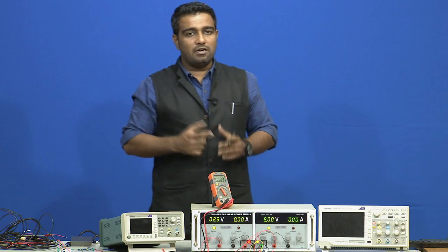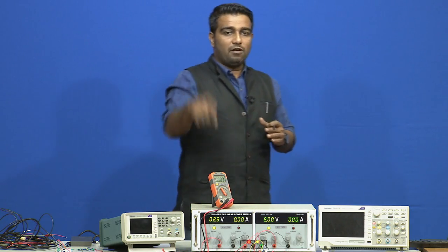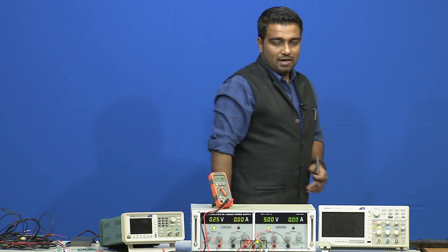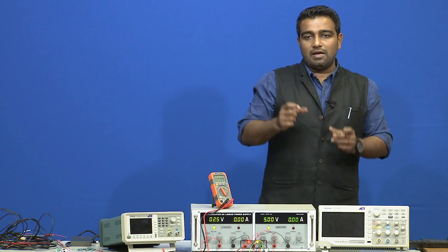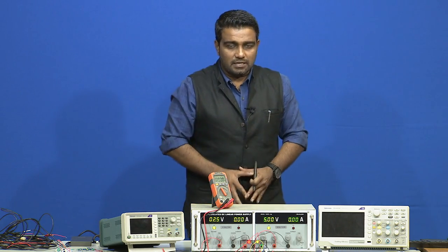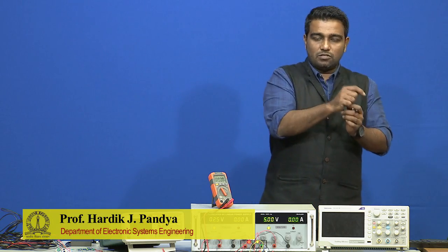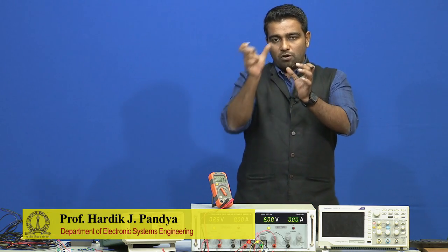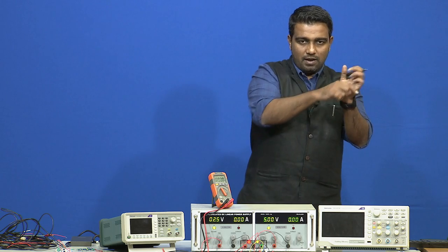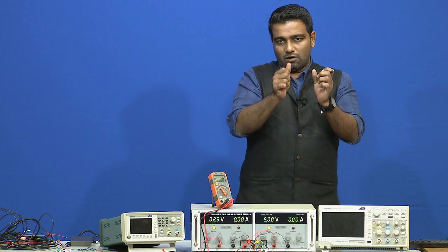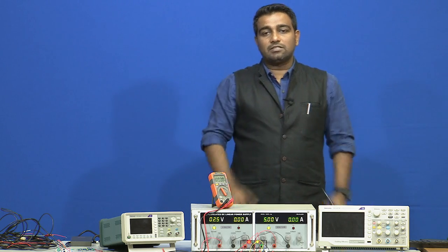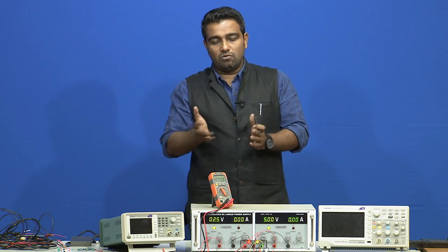So, understand this thing, until and unless you ground the circuit it will not finish, right, you cannot keep it hanging. So, same thing when we are using an LED with a current limiting resistor, you have to ground the LED, right. So, one is resistor, output, resistor, LED, ground, alright, and cathode is ground, not anode is ground, cathode is ground. So, the LED works in forward bias, you should know it.